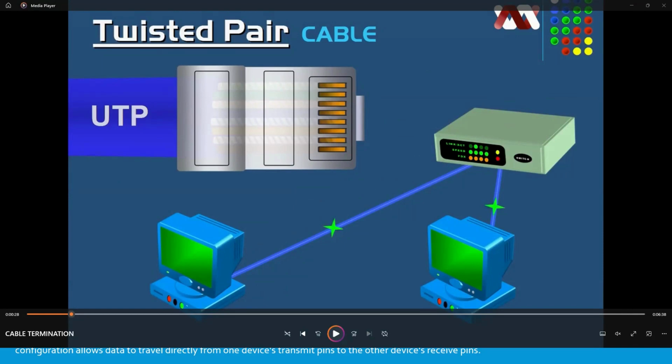You can do your own color management, but it has to be the same. Whatever the color management on the A side, the B side should be the same, should not change anything. So both terminated ends should be the same cable. So it's kind of straight, right? So you have straight cables. You can do any color changes, but make sure you follow the international ones. It's much better.